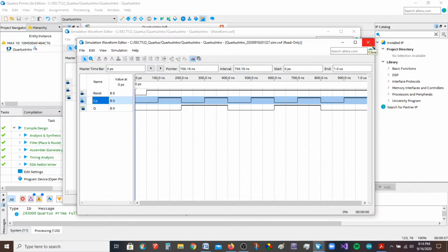Okay, I think that's enough for this session. If you wanted to, you could connect the clock pulse to one of those pins on the board and then use an asynchronous reset on your actual physical proto board and download it and then see how Q changes on the LED. The problem is that the clock pulse is super, super quick. So until we talk about Chapter 12 where we do the modulus, which if you go back and look at your 112 notes, you should know how to do that, you could knock that 50 megahertz down to something more reasonable to where you could see the LED flicker on and off if you wanted to, okay?